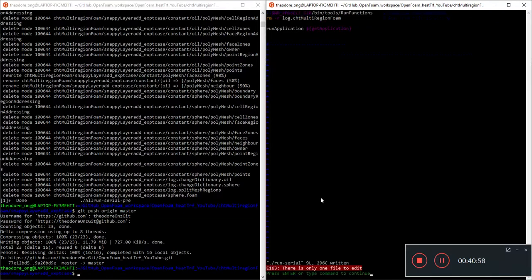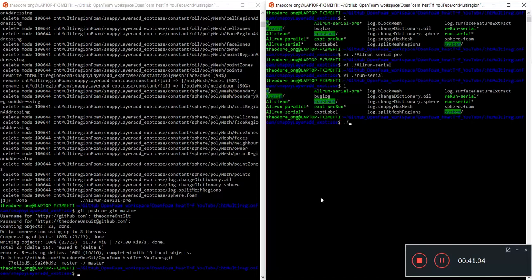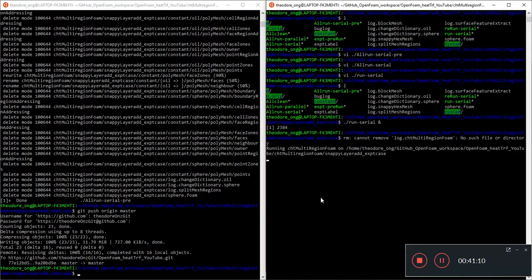Okay, oopsie. Quit all, and we do a run serial, and to run chtMultiRegionFoam. Okay, so that will start running chtMultiRegionFoam. So in the next video we can discuss the results to see what the heat transfer coefficient is like.